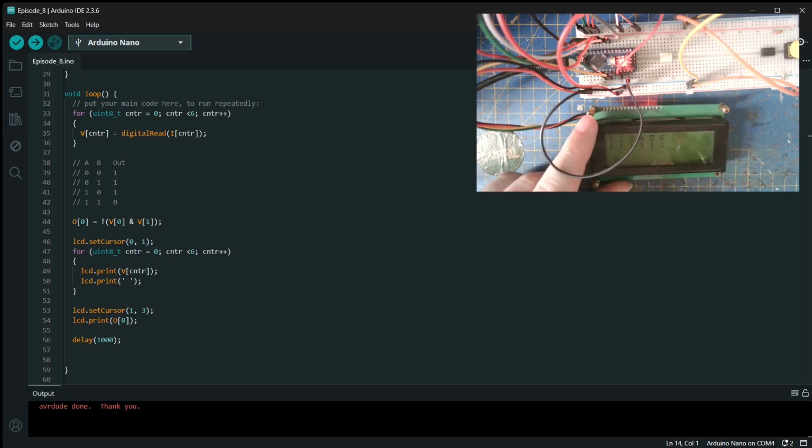Leopard Street, for example, my board controllers have got, as I mentioned, the little screens. The reason they're there is so if I tell a point to change and nothing happens, I can go down and look at the screen. And the screen will tell me what the controller thinks the point is doing. So if the controller says the point's changed, and it hasn't, I know there's a problem with the hardware. If the controller says, you've not told me to change it, I know it's a network issue sort of thing. So it helps with debugging.